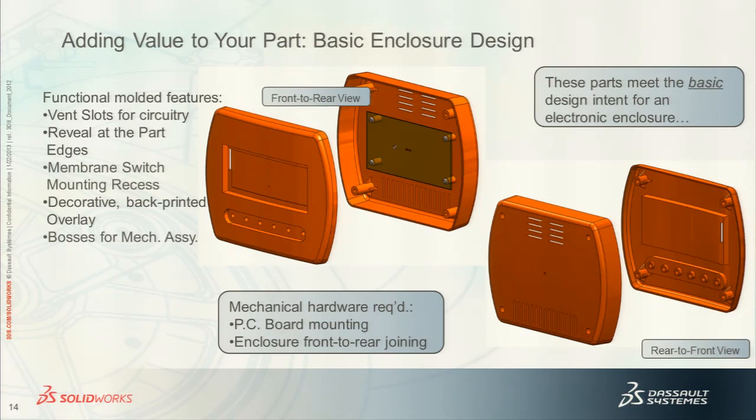That's a pretty standard method of mounting a circuit board in an enclosure. I have vent slots on the backside to help dissipate heat that the circuit board is creating. I have a membrane switch in this recess with a back-printed decorative overlay. So it's a pretty standard electronic enclosure design.